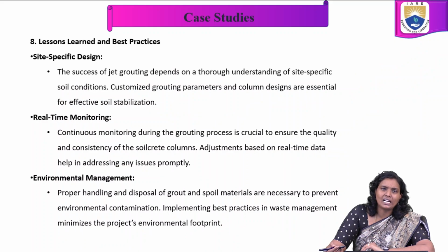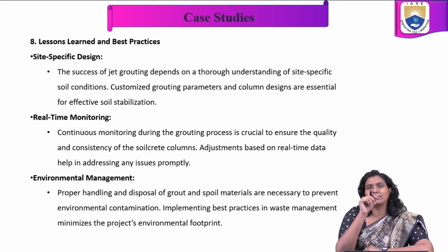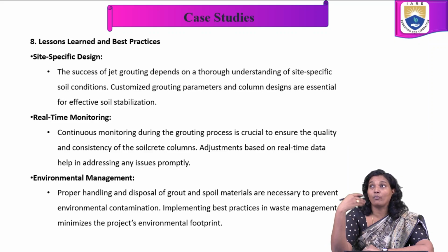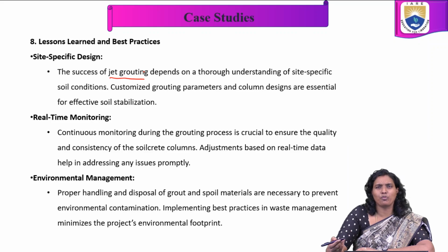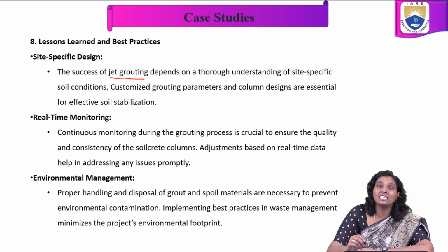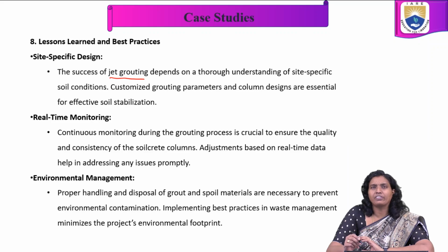Site-specific design, real-time monitoring, and environmental management are the lessons we learned. These are the best practices for any kind of technique. For this particular technique, site-specific design is very, very important. We have different types of jet grouting, and there are also replacing jet grouting techniques in ground improvement. Choosing the right technique is one of the best practices and important to learn from these case studies.